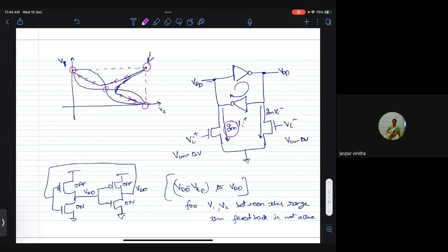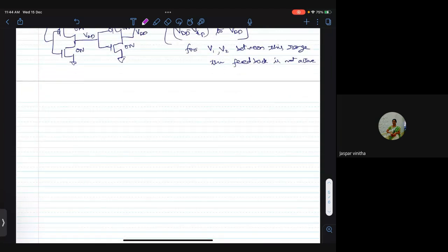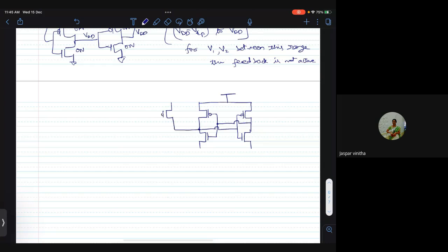Okay, so this is the circuit basics, the heart of the circuit. Now, I have shown this, but how do you actually connect it up in the whole picture? That's very easy. I will just show you the full circuit here. So this is the inverter, one of the inverters. Okay, I have to connect this in positive feedback. So that is what I will do here. Okay, and initially I need to pre-charge these two outputs to VDD. For that, I will have a PMOS transistor, which will be driven by the clock. So whenever the clock is 0, this output will be charged to VDD.